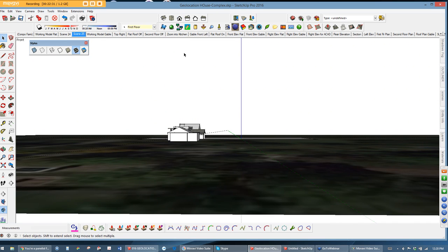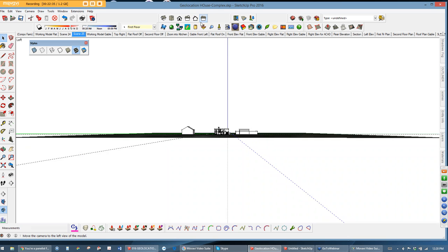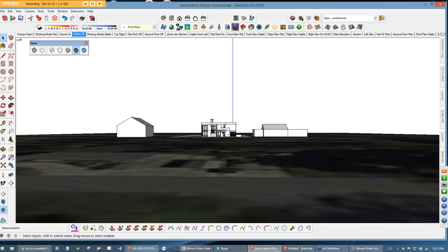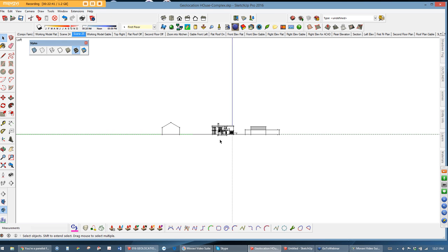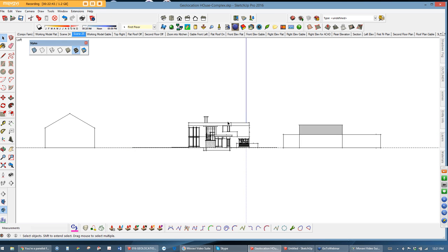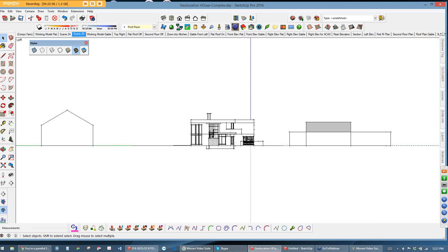If we go to front, let's say side of some sort, the other side. We can actually create, if we go to parallel projection, an elevation of the neighborhood, which I've had happen before. Actually, outside Chicago, I had to go measure 6 buildings up and down a street and draw them all, and then draw my building and what do they look like next to each other.